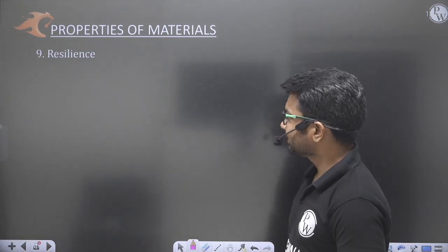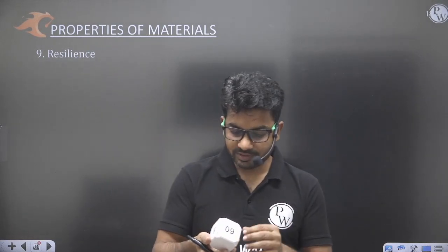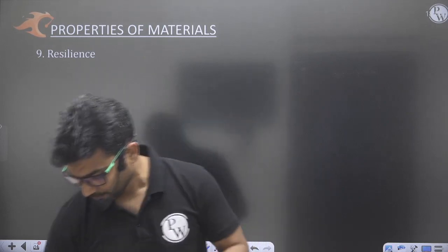Next is resilience. Now what is resilience? Resilience is the strain energy stored in the material. If we apply some load on the material, because of this load there will be deformation in the material, and because of that deformation there will be some strain energy stored in the material. The strain energy stored will be equal to the external applied work.